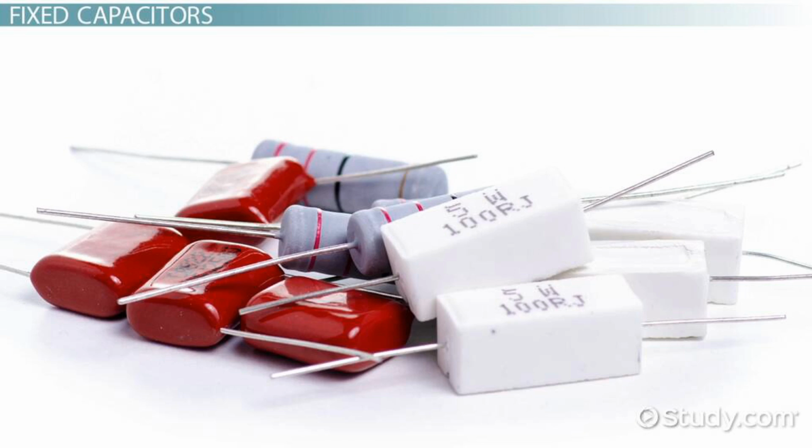7. Snubber circuits and power switching devices. Film capacitors are used in snubber circuits that protect power semiconductor devices like transistors, IGBTs, and thyristors from voltage spikes during switching. These snubber circuits are commonly found in power conversion systems, motor drives, and high-power inverters, helping to absorb and dissipate excess energy to prevent damage to the power components.